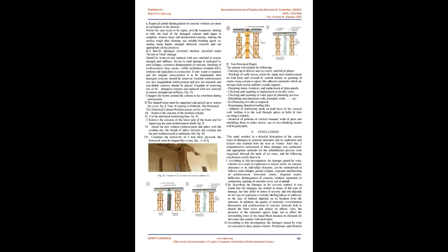cracks or voids. Dry packing is the hand placement of a very dry mortar and the subsequent tamping or ramming of the mortar into place, producing an intimate contact between the mortar and the existing concrete surface. The low water/cement ratio of the material reduces the shrinkage potential.